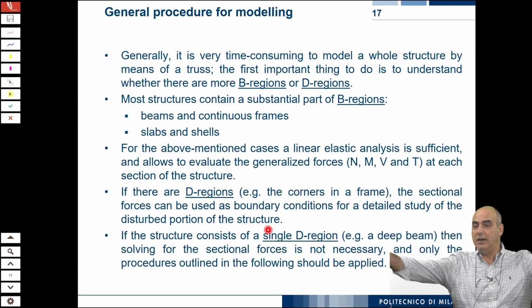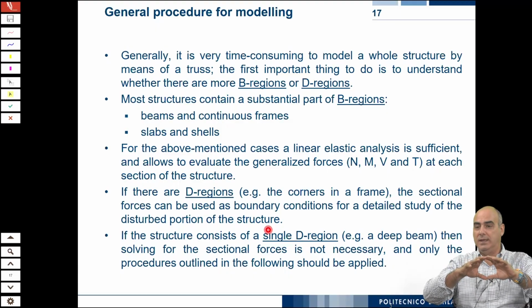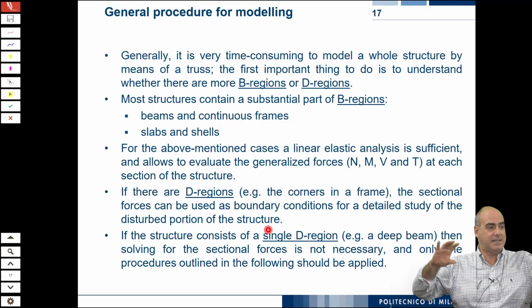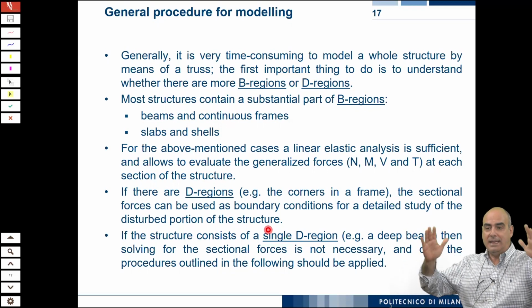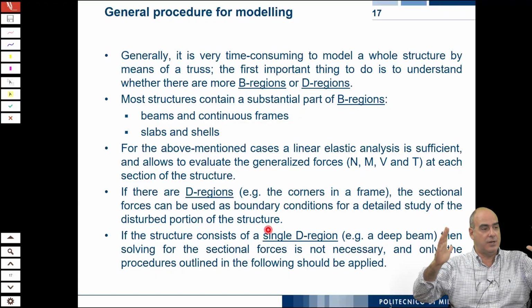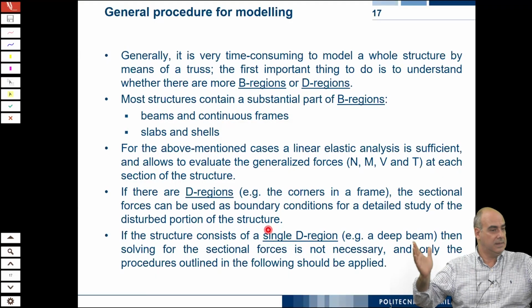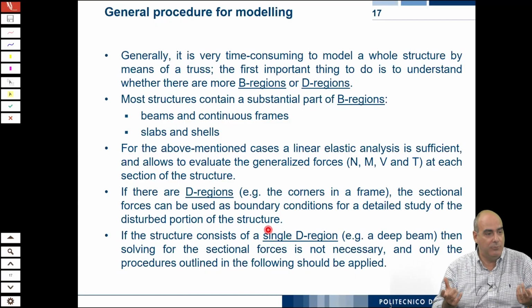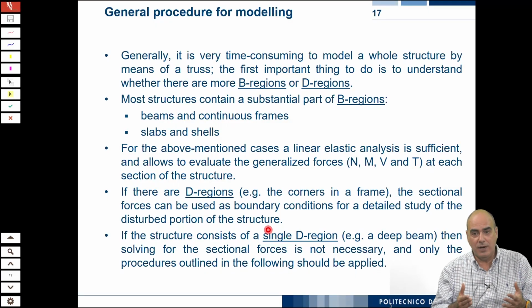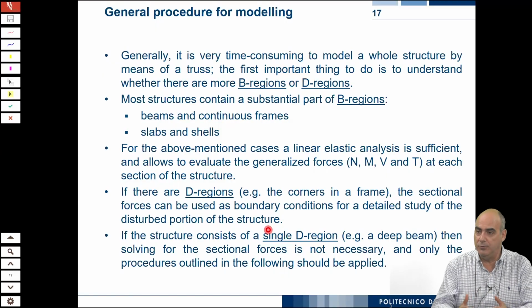In solid mechanics theory, we work with the De Saint-Venant solid, which is a solid that floats in the air and has loads just on the edge cross sections, and these loads are in equilibrium. So it's an ideal model, but in reality we have boundary conditions. A structural element has a geometry, but has boundary conditions as well.